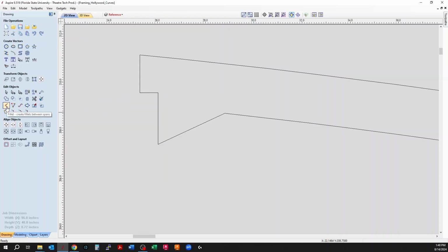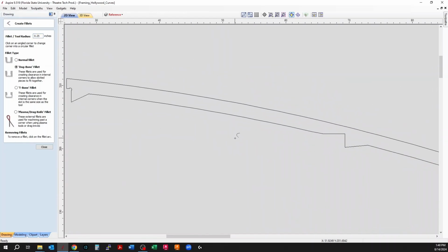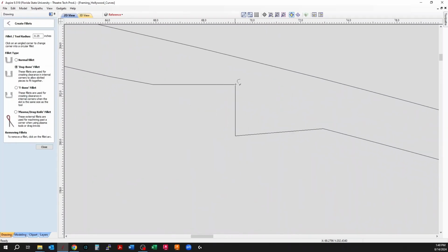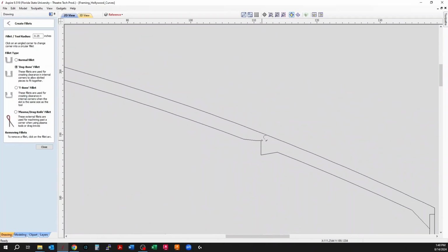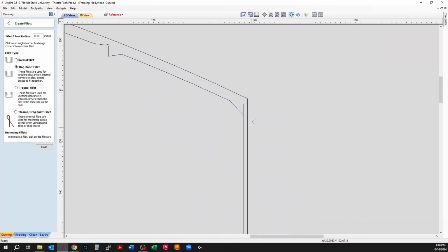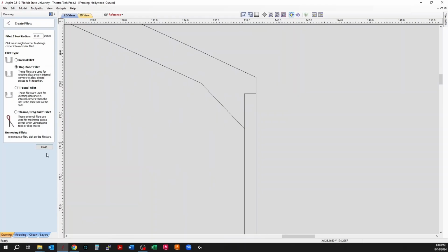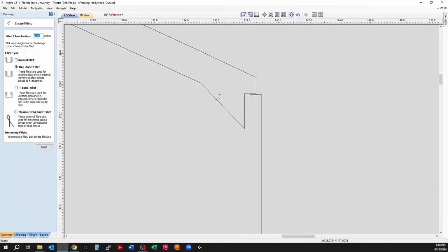That's real easy to do here with this fillet command, and you can do a dog bone. Right here I've got set up a 1/4 inch radius, and I'm just going to hit that corner, right? So now that let in will allow my flat piece to go flat into that corner, right? So easy. I just want to make sure that I'm getting the right thing. Here, I'm just going to move that away. Go back to my fillet command, dog bone, boom, right there.